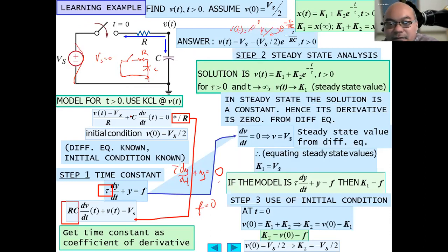Yes, so when we have Vs, like what is presented in this line, first we have to eliminate this denominator by multiplying each term with R. So R multiplied by this becomes Vt minus Vs plus Rc dVt dt. Then the Vs term is not the variable that we want to calculate, so we move it to the other side of the equation.